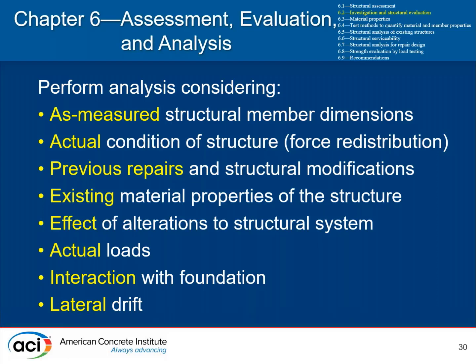And so the actual conditions of the structure, the deterioration, or what is actually in place can impact how forces are being distributed, potentially to areas that weren't intended originally, however, are acting in that manner given the deterioration or previous or current repairs. So previous repairs and structural modifications need to be confirmed.